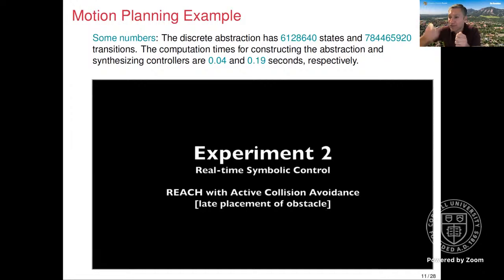To keep track of the sojourn time. And that's a good thing with the symbolic techniques, because memory is just an extra discrete variable I need to add to keep track of how many times I have a state in that mode. And that's how we are able to ensure, for the switched system, stability or safety: we keep track of the sojourn time in each mode, and then we change the switching signal to ensure the overall safety of the system, or stability even.